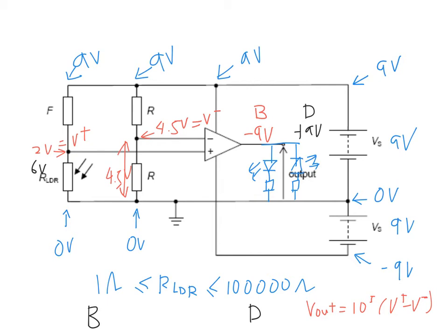Okay, so now remember you said when it's bright you want a green LED. So which LED should be green, the left or the right one? How do we know? Remember when it's bright, you get negative 9 volts here. So which LED will light up, the left or the right? You check and see which one is forward biased. Can you see this is 0 volts? So current now will flow through 0 to negative 9, right?